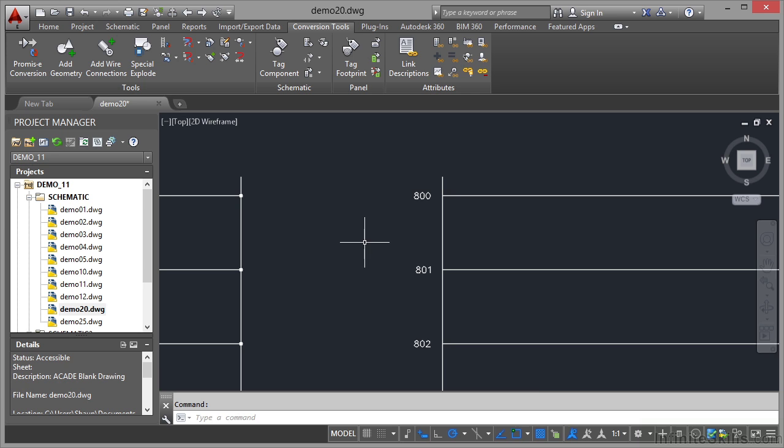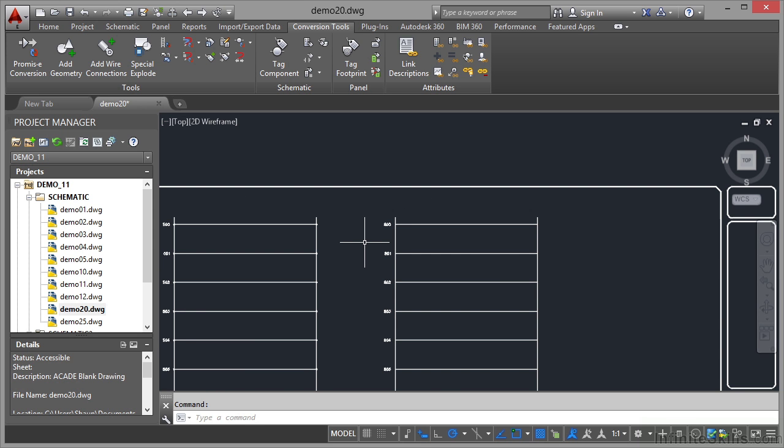Now the reason I've done that is obviously I might have a drawing that's come in from a third party that hasn't used AutoCAD electrical. So it will purely be lines and text representing my logic ladders on the electrical drawings. I need to convert that information to make sure that those numbers on those ladders get picked up if I do a numbering project-wide where the numbers change on the ladder.